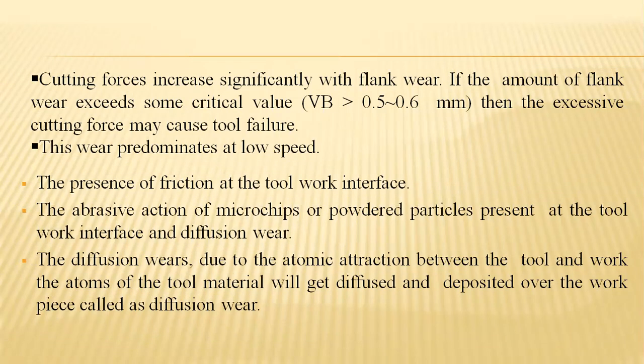The burr predominates at a low speed due to the presence of friction at the tool-work interface, and the abrasion action of these microchips present at the tool-work interface causes the diffusion wear condition during the machining process. Normally, this diffusion is due to the atomic attraction between the tool and the work material, which gets diffused and deposited as a layer over the workpiece.